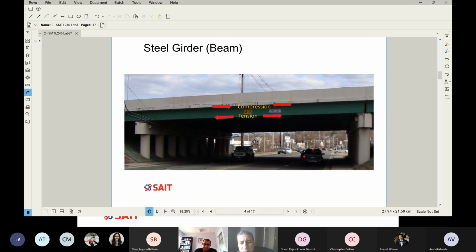So this is very typical bridge construction, which is made out of beams, but since the beams are heavier than normal beams, we call them girders. So it will be a series of these girders. You can see those green ones, we call them girders. You can see the span between those piers, like this one and this one right here. They are simply supported and under gravity load. So if my load is going down like so, you will see the bottom chord will be in tension and the top chord will be in compression. So bottom chord in tension, top chord in compression.